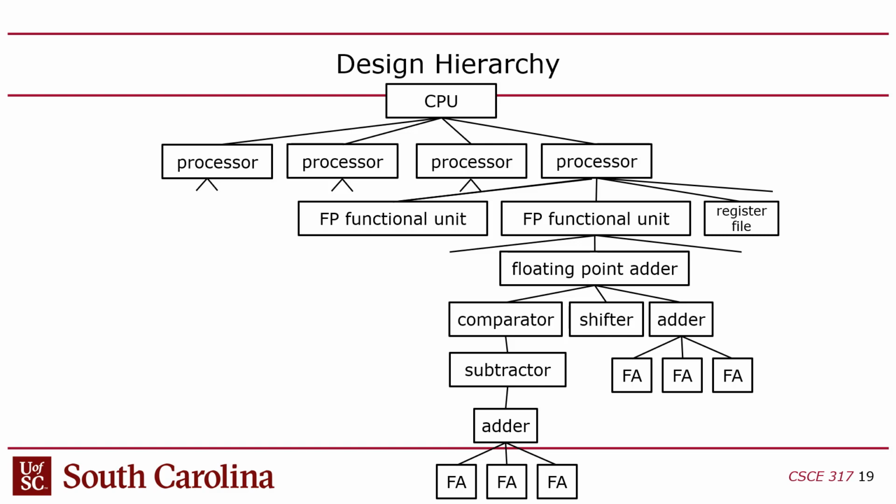The reason why chips have so many transistors is because they're designed with this hierarchy, and they're designed with regularity, where 90% of it is copied and pasted structures that repeat over and over again, right? So that's the reason why you can have such high levels of integration, and that's what SystemVerilog is doing for you, giving you the ability to very easily create these design hierarchies.